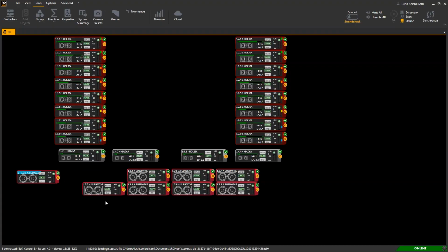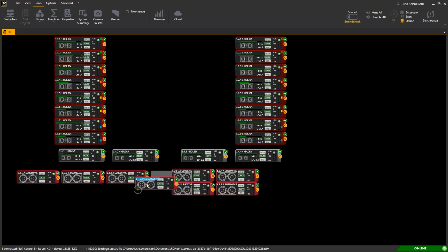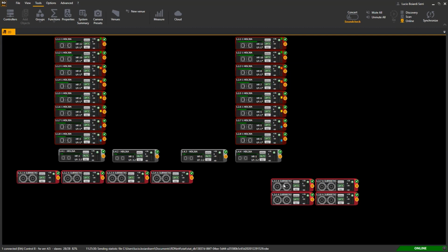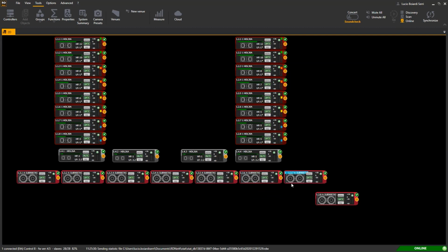This video is about all advanced functions that are useful to control subwoofer array directivity in a simple and intuitive way with RDNet. The curve function allows the natural curvature of a horizontal array made of equidistant subwoofers to be electronically simulated in order to control its horizontal polar pattern.